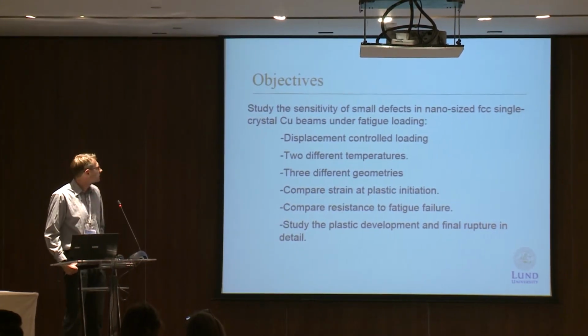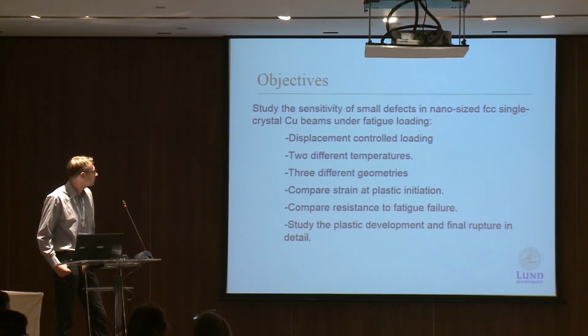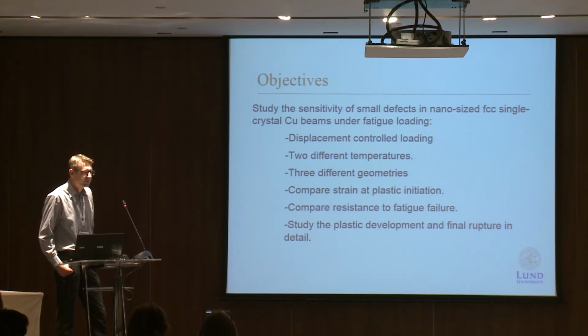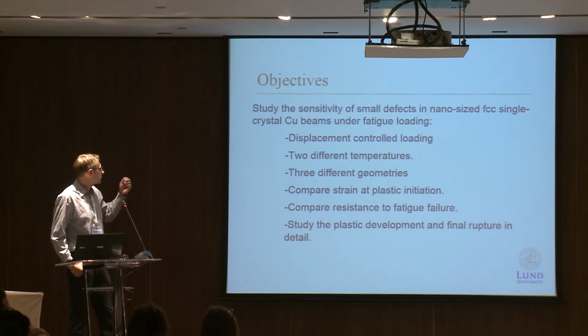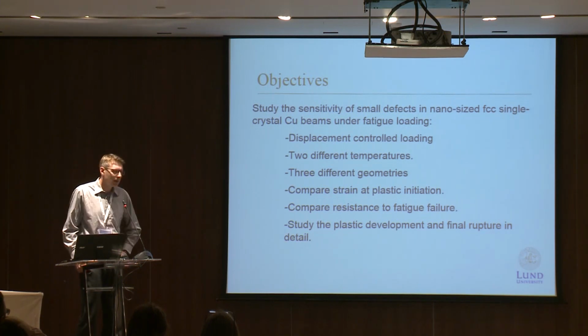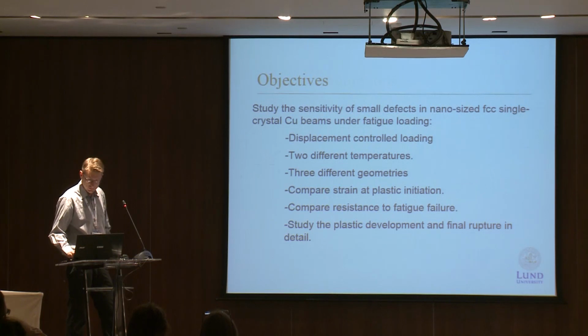To do this, we have used displacement control loading. We have looked at 2 different temperatures to see how it impacts the results. We have looked at 3 different geometries for different defects. We have compared these different simulations regarding strain at plastic initiation and also strain at failure. Then we have compared the resistance to fatigue failure. And we also studied the plastic development in detail to try to understand what really happens inside the material.